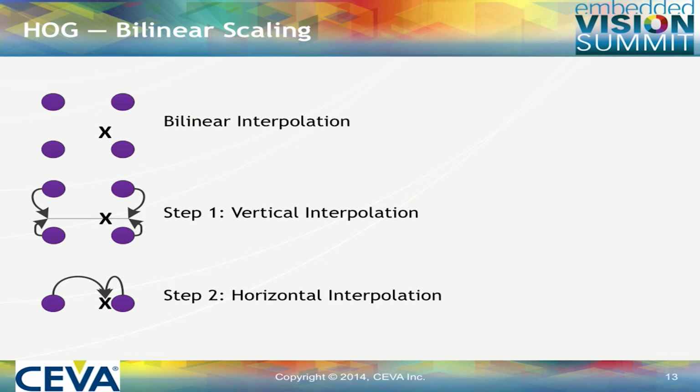This is challenging for a SIMD DSP architecture, because usually what SIMD likes to do is load 2 vectors of linear data and then do some computation. So step 1 is very efficient for a regular vector processor, but step 2 is not so much, because how do you do intra-vector calculation? And I want to do it in a SIMD fashion, on many data at the same time.